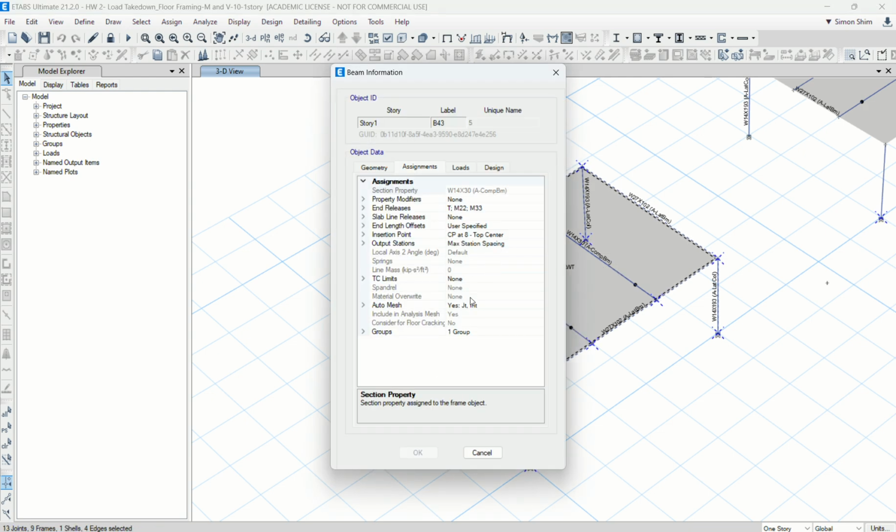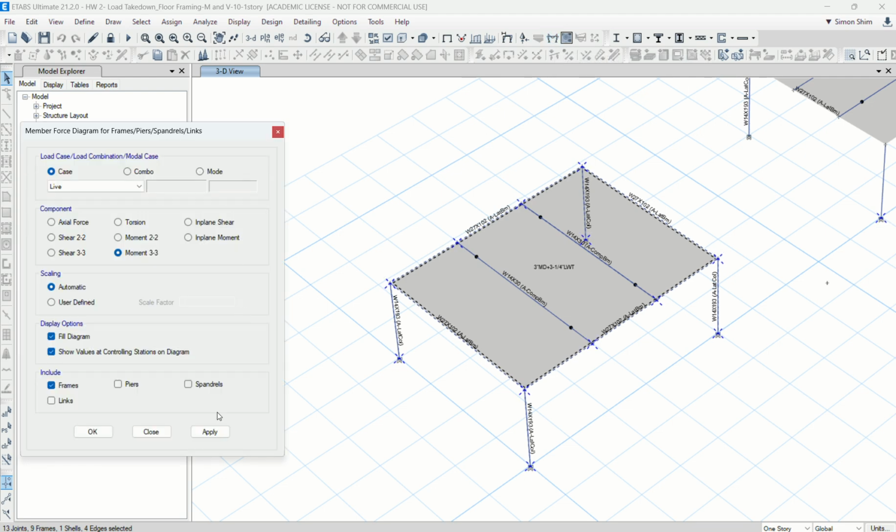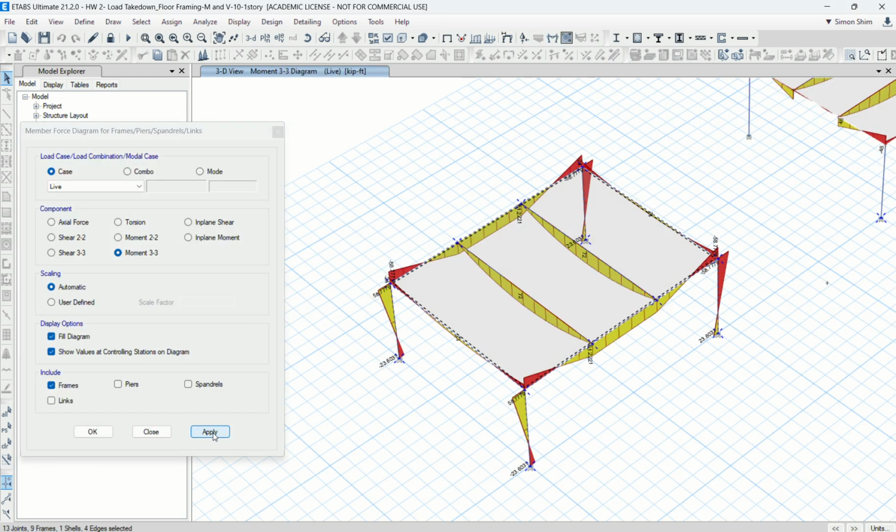When you turn on the property, you see that the angular moment is showing as released. So at least this is something I want you to run in this model, think about it, and double check the moments based upon the loading, with just a hand calculation to confirm. Simple math.